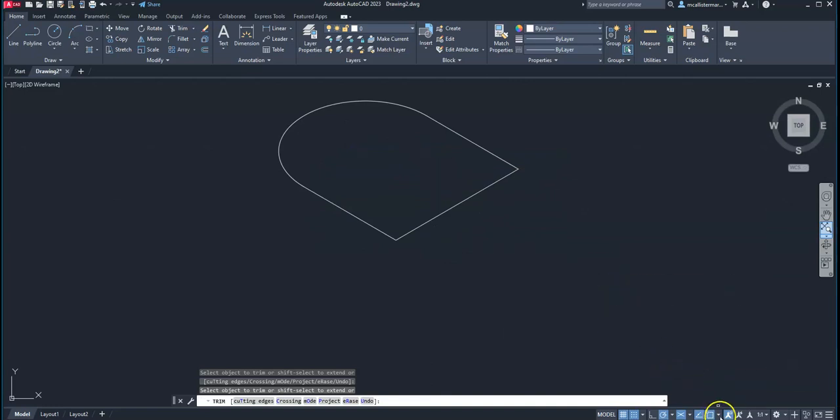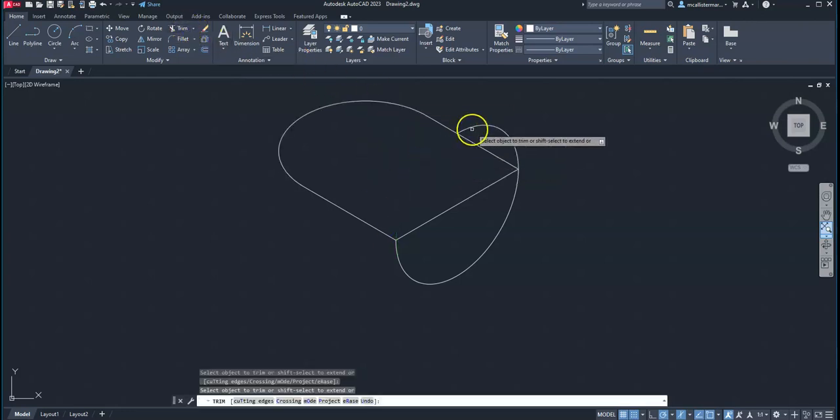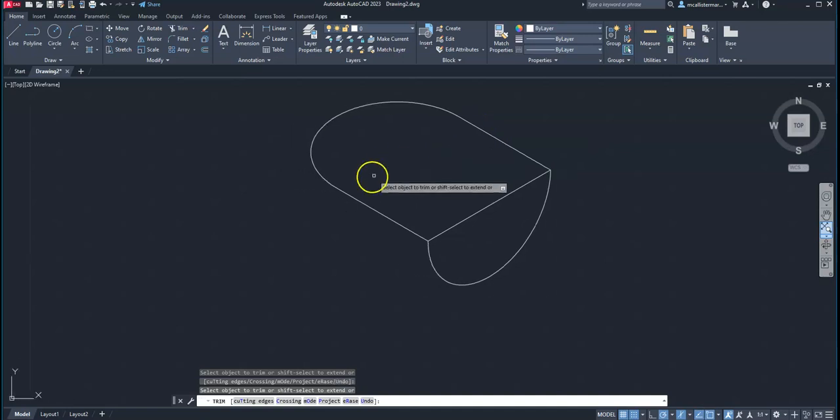Another thing we can do is we're going to flip to isoplane right. Let's type ellipse again and hit enter, hit I and hit enter. And along here, I'm going to draw for myself an IsoCircle. It just goes right along here. I'm going to go back up to trim, and we're going to get rid of just this part and this part right here. And it's kind of cool to see how we can create these IsoCircles on different planes for different purposes. We could even eventually get into the tangent constraint and draw a line straight down, make these things come out and meet each other.